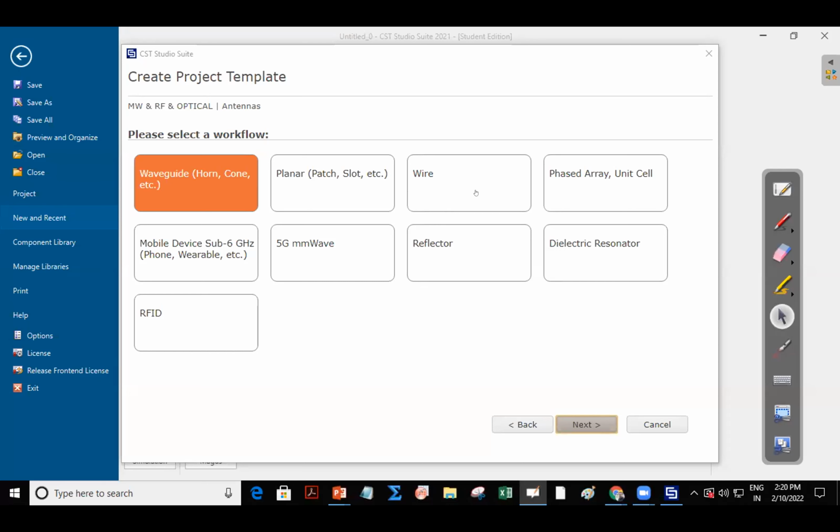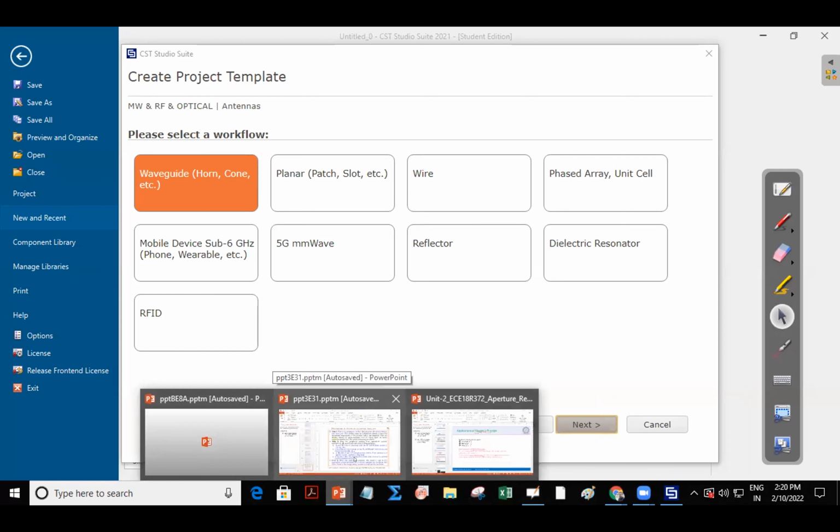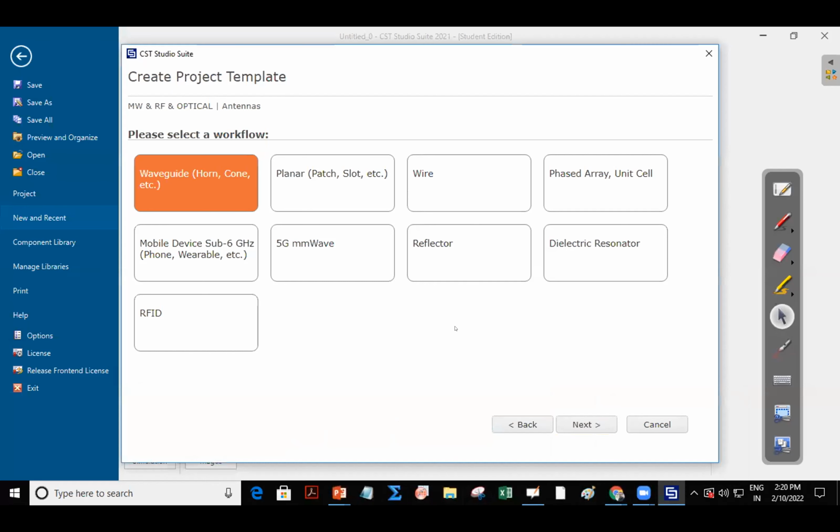Now, one important thing is about a wire antenna. If we say this is the loop antenna with a number of turns, it needs some base, because loop antennas are placed in a vertical plane, or whatever plane, and the loop which is not connected should have some support or base. That's why they are generally made as planar or patch type antennas. If you make a wire type of loop antenna, it is only used for one or two purposes.